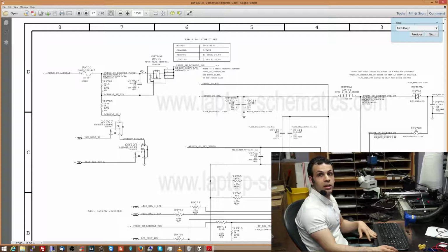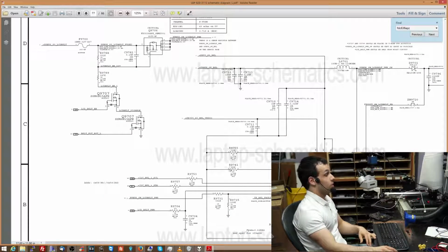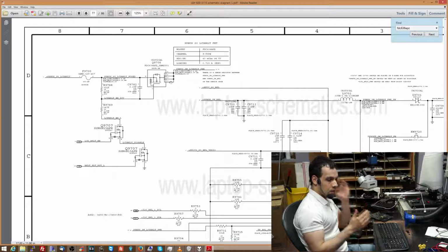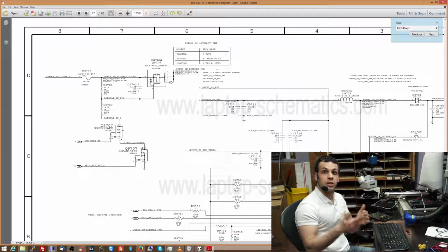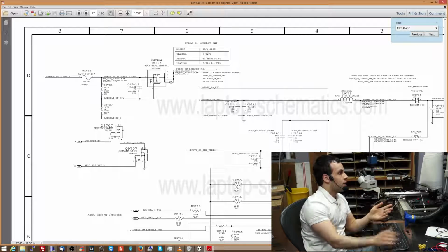Now you may be wondering, it doesn't say what the resistance of the resistor is. So over here, this resistor is 0 ohms. Over here, that resistor is 10 kilo ohms. Over here, that resistor is 33 ohms. But what is the resistance of this resistor? Well, the resistance of this resistor between the source and the drain is set by the gate. So the voltage on the gate is going to be what adjusts the resistance. So think of this like a resistor whose resistance you can actually vary. You know how they have those dimmable incandescent lamps where you can have low, medium, bright, and off? It's the same idea here.